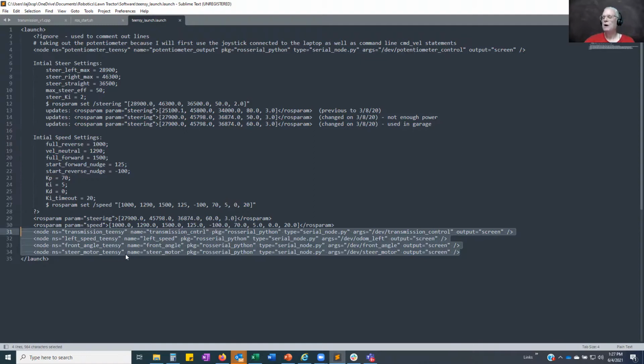Now, I believe you also have the command velocity mux on the laptop, so that passes directly into that. But the other input to the velocity mux is the navigation stack from the TEB planner, which is on your robot. So it's having to generate a message and send that across to your base station to the velocity mux, and then it puts out a command velocity which gets sent back to the robot again. So now you've got extra traffic going back and forth. If you just move your command velocity mux out to your robot, then those extra transfers would go away.